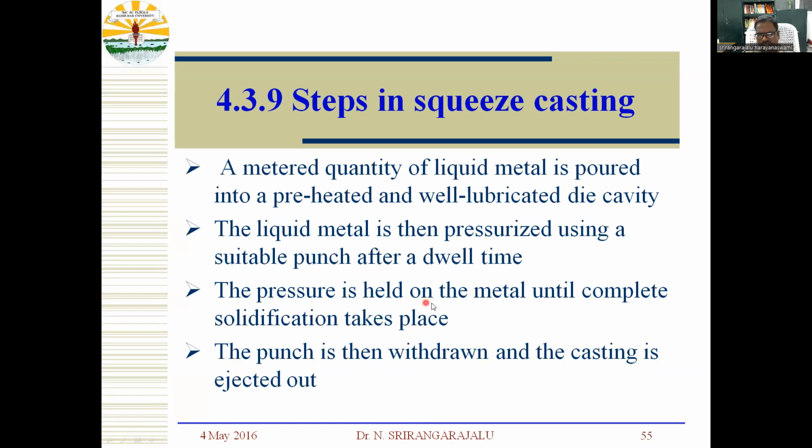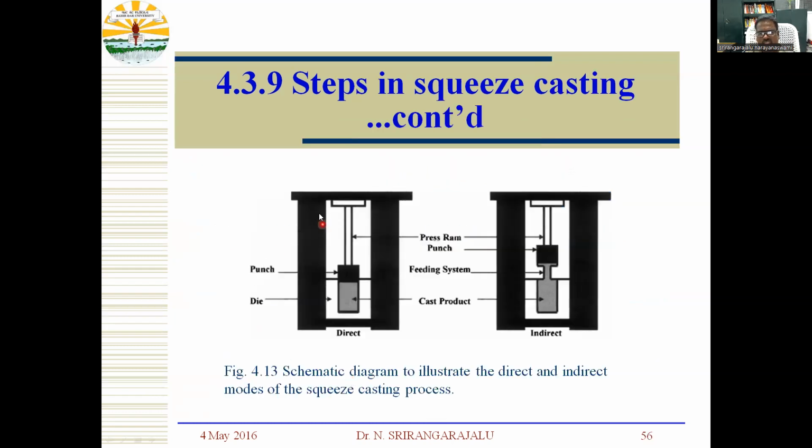The pressure is held on the metal until complete solidification takes place. The punch is then withdrawn and the casting is ejected out. So these are the steps in squeeze casting.